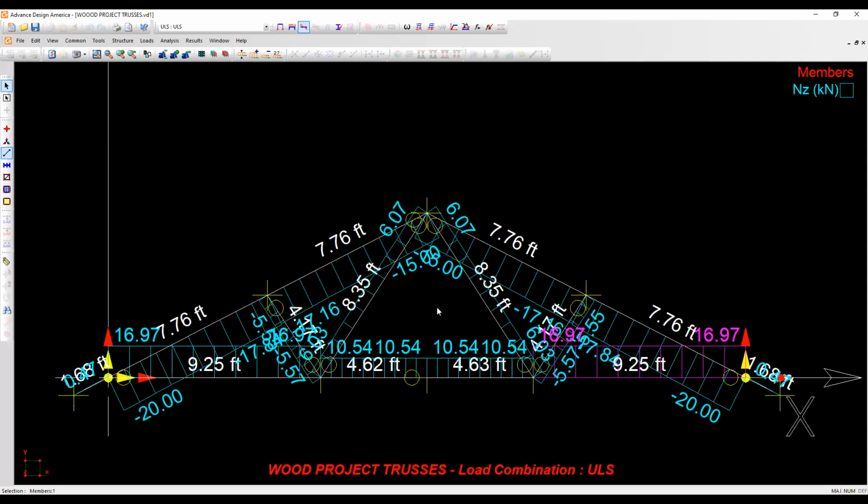And if you go into the table and look at the TR value of a 2x4, and multiply by 1.1 because you have a case one system, I think you end up with something like 25 kilonewtons, your TR value. So whether this is 6.4 or 5.3 or 8.2, is it going to make a difference? Not that much, because your TR value is way over your TF value. So you understand? It doesn't make much of a difference.